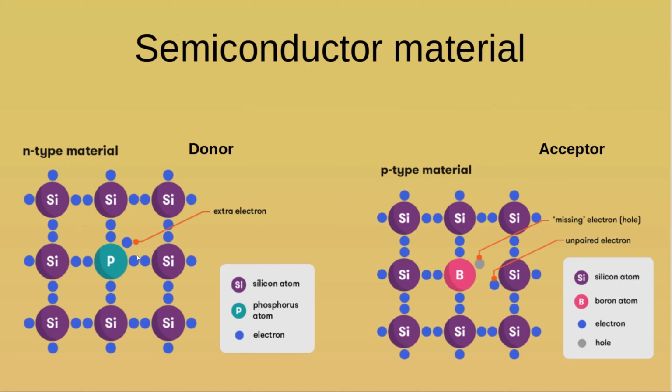So it becomes basically a free electron and gives that crystal a negative charge. In the P-type material, one of the common ones is boron, which is only 3. So we wind up with another mismatched pair. In this case, we've got a hole. So that becomes an acceptor.